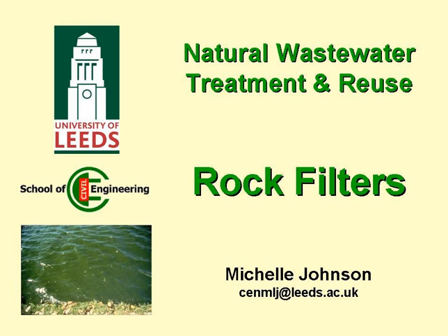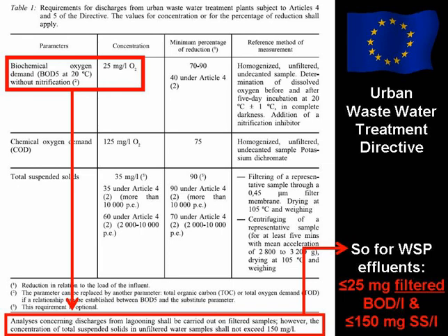This presentation is on rock filters, which are used to polish the effluents from waste stabilisation ponds. In the European Union, wastewater discharges are governed by the Urban Wastewater Treatment Directive. This table is taken from the directive, and it states that effluents from wastewater treatment plants should have a BOD no greater than 25 mg per litre.